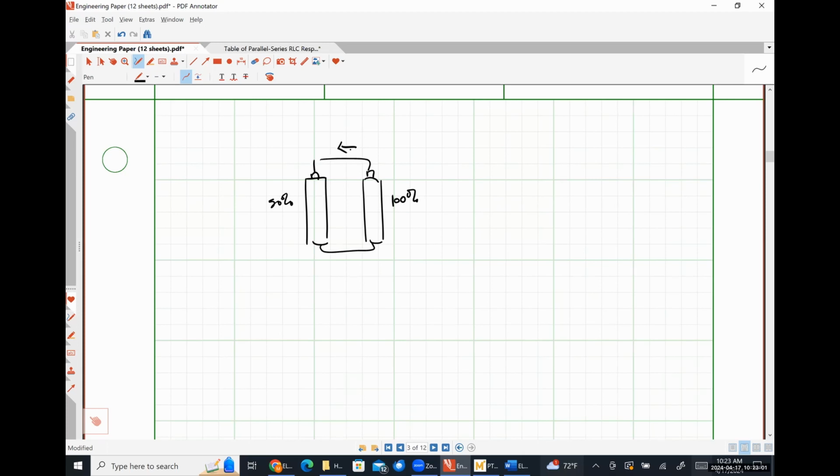Outrunner motors to me are really interesting. An outrunner motor effectively works like a DC motor. You've got all these different coils and you use MOSFETs to switch on different coils at different times. It's producing a magnetic field that is attracting a permanent magnet connected to the rotor, so it's just dragging those along in sequence. However fast you switch your MOSFETs on and off is however fast the motor spins.